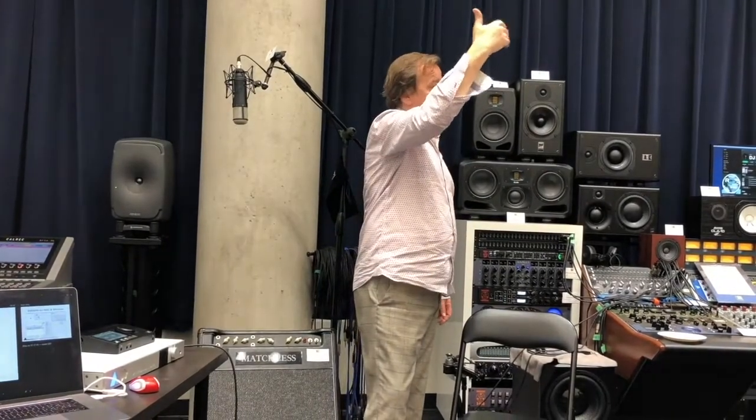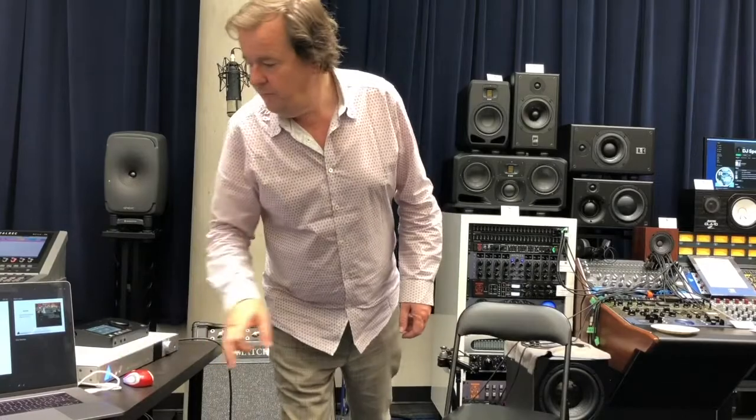But then the advantages of the AES67 is that you can have multi-sample rates in a studio environment, in different studios, for example, on the same network, and you have high track counts. If we talk about immersive audio or higher sample rates, then the high track count enters into something serious, where in the Dante world you're limited about this. Okay, so these are a few advantages about that.